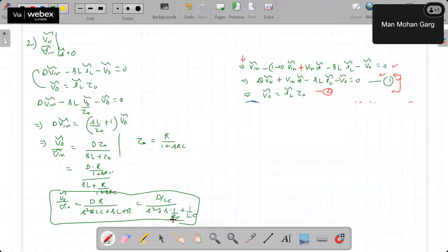If no, then how to designate current and voltage for 3 switches. You take any one current and any two to be voltage. If there are 3 switches, then you designate VSW, ISW. In each mode, get the current and voltages across each switch. Note the time interval of each mode.